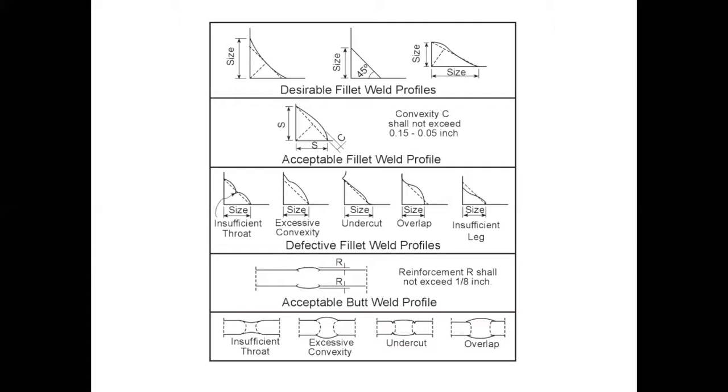So those vortices actually create weak points on the downstream side of those welds due to the turbulence it creates inside the pipe, and that's where pipe fails. It wouldn't be the weld that failed, it would be the wall of the pipe slightly downstream of that weld. So that is why we try and avoid that. We try and avoid any intrusion, major intrusion into the inside of the pipe.